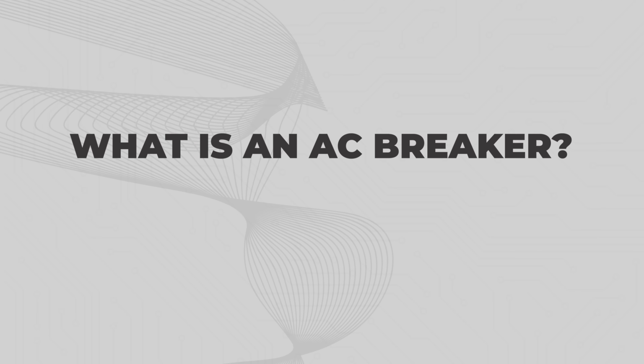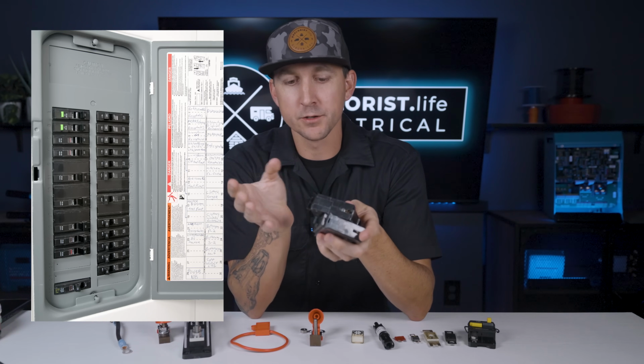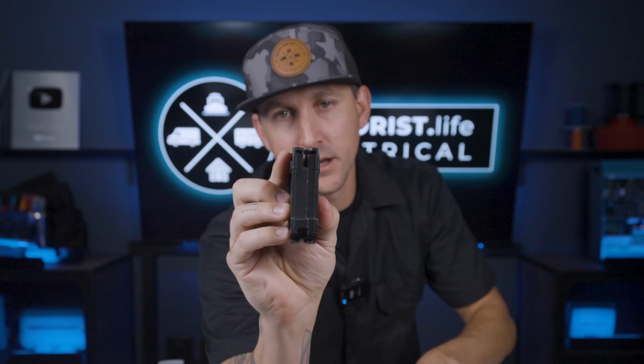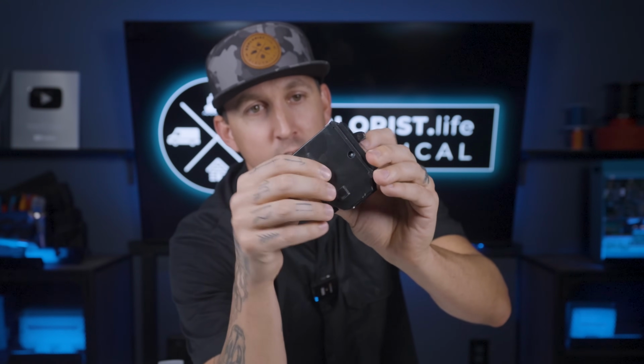So what is an AC breaker? An AC breaker is pretty typical in US households in your standard residential breaker box. They've got a slot here on the back where power comes in and a screw terminal on the bottom where power goes out, and that's connected inside by the breaker mechanism that will be connected under normal operations and then disconnected if you need to do maintenance, but more importantly, if there's an overcurrent event like a short circuit or the circuit is overloaded due to overuse.